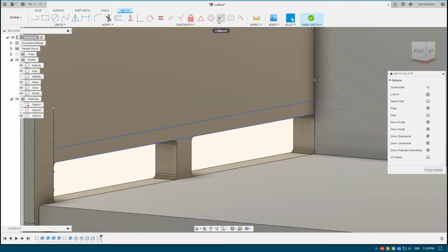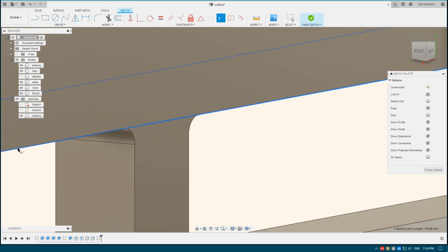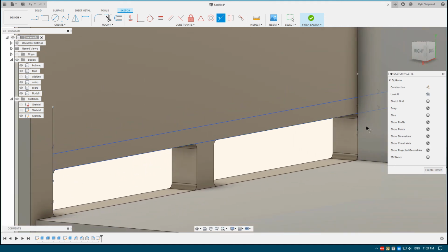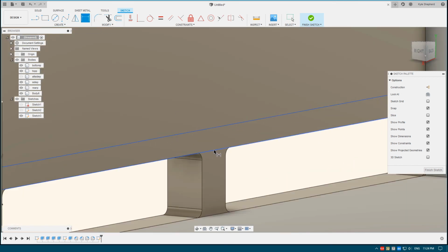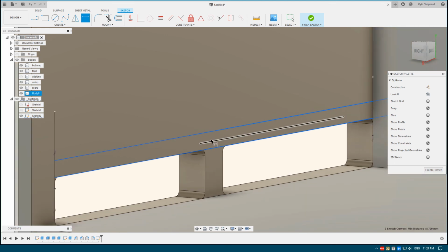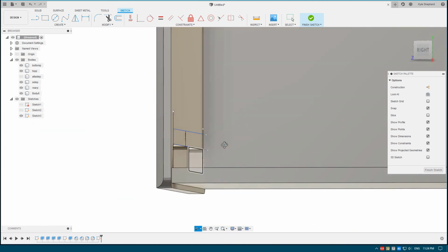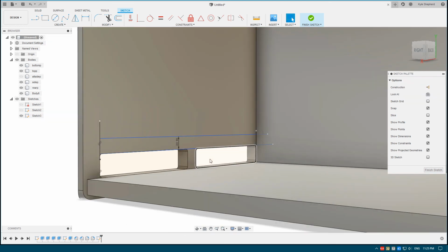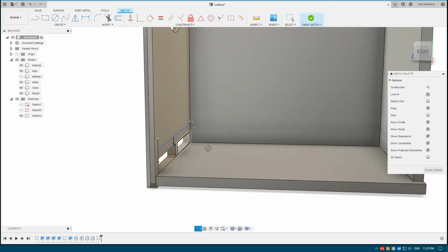Okay, so now we'll apply our constraints. So I want this to be constrained with the top of that port there. And that's already tied to this, and this is already tied to that. So now we just want to set our height here, which is of course 16 millimeters, because we'll use the same thickness MDF for that. We'll go to perspective again. Probably could use thinner sheet. Nah.